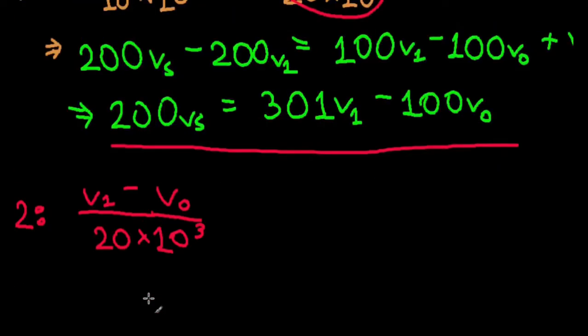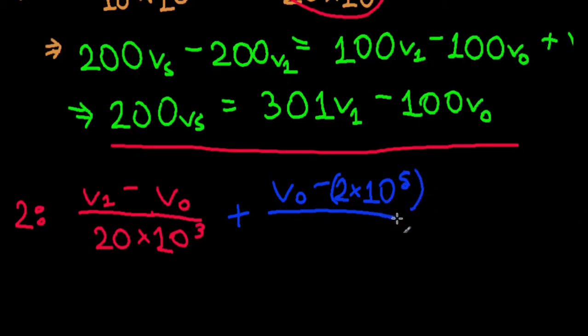So first of all, let's just write the current as it is. So we have V0, as we said. So V0 minus A times VD, and it's going to be divided by 50. But before writing that, I'll just simplify this one. As we said, A is 2 times 10 to the 5, and VD is negative V1. Okay, and I can make these two positive. Negative negative becomes positive. So that's a fair bit of simplification. Divided by resistance 50. All right.